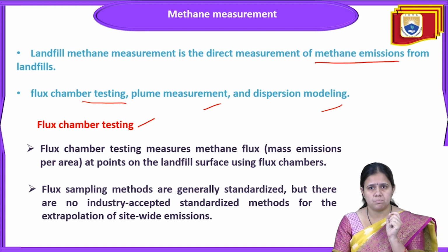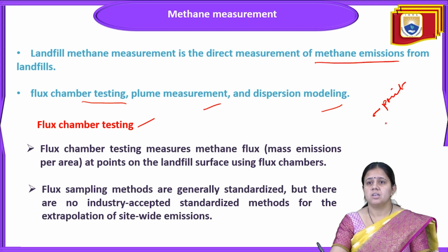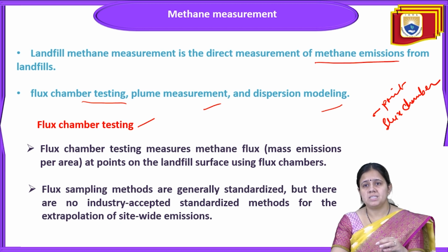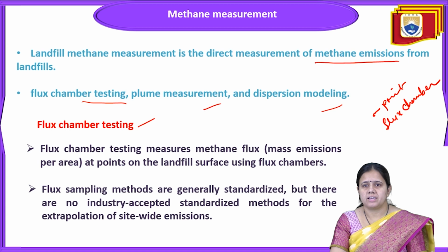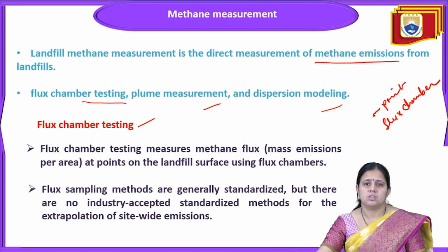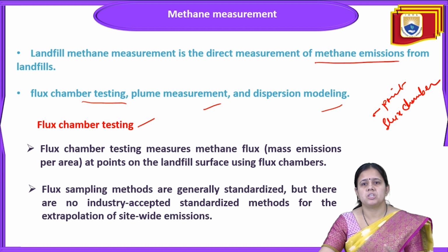Using flux chambers on the landfill surface, the methane flux, or methane mass emission, is measured at sample points. The flux sampling methods are generally standardized, but there are no industry accepted standardized methods for the extrapolation of site-wide emission. So this flux chamber is a testing measure of methane.